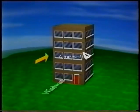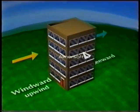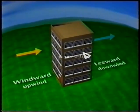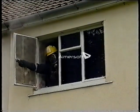Wind flow around buildings can be complex, but at its simplest, the windward side or approach side is called the upwind side, and the leeward or departure side is the downwind side. This will create a positive pressure on its approach at the upwind side and a negative pressure on the downwind side. This pressure difference will assist the process of ventilation if the outlet vent is downwind and the inlet vent is upwind.